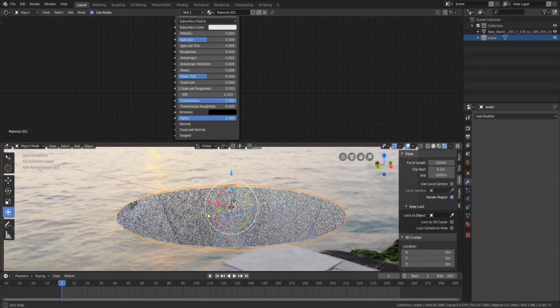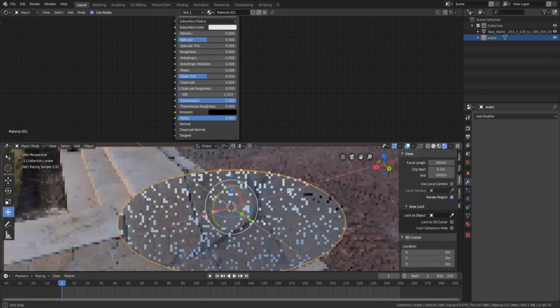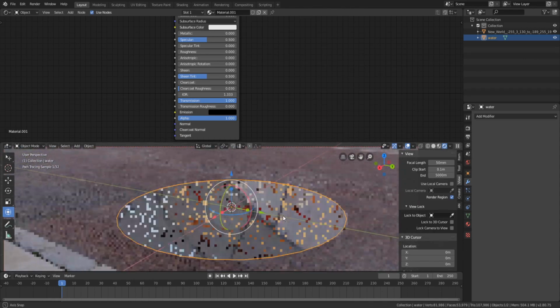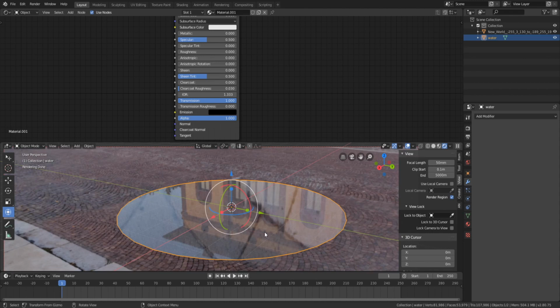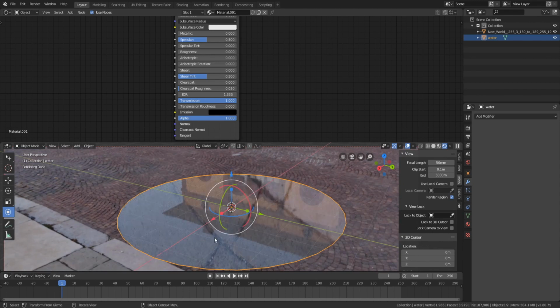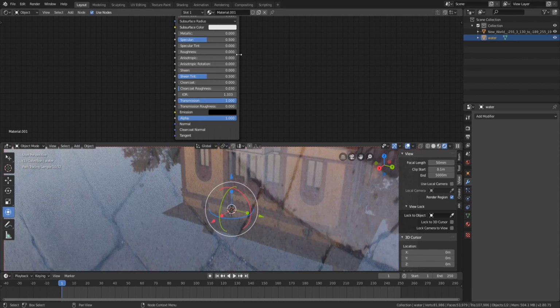You can sort of see that it's changing the way that the light is hitting it, which is exactly what we want, because whenever you look at water, it sort of has a reflective look because it's reflecting over there, but then also you can see the stone down there because of how the light is reflecting off of the glass, which is what we want. Now, next thing I'd recommend is actually changing the roughness to 0.05 or lower, probably like there.